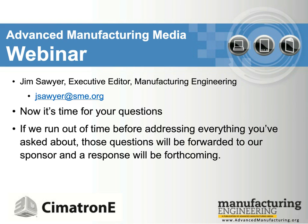Does Cimatron support 4- and 5-axis machining for reducing electrode setups? Yeah, so I know that a lot of companies are taking advantage of trunnion style electrode setups so that they can lay the electrode down and cut it from different orientations.